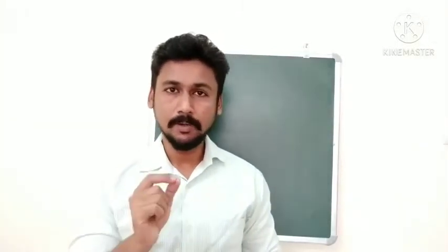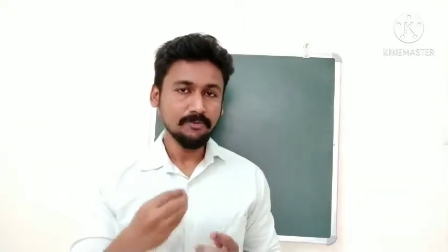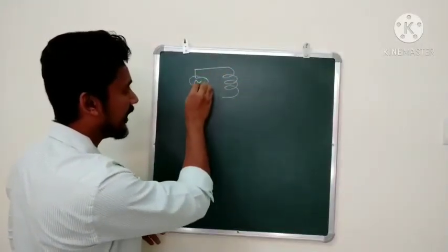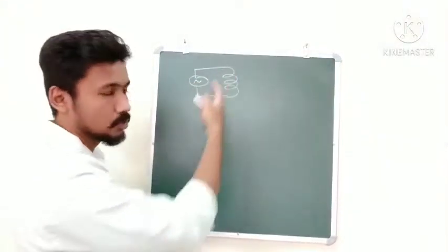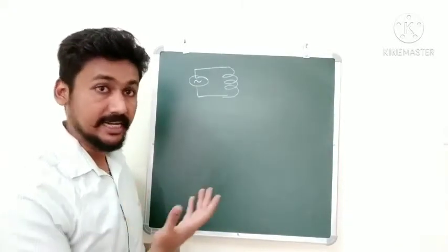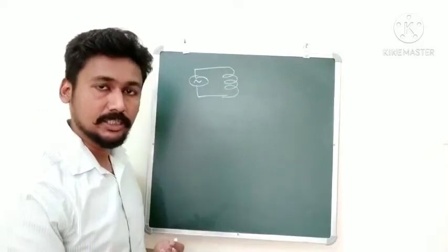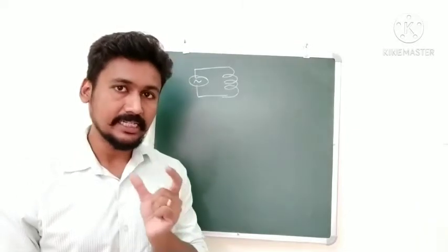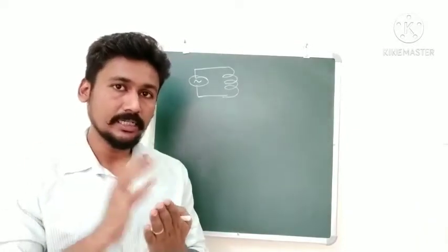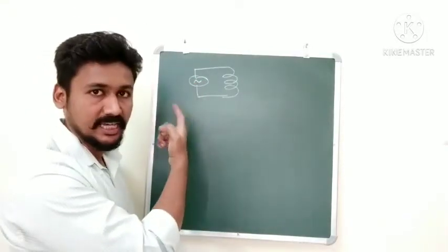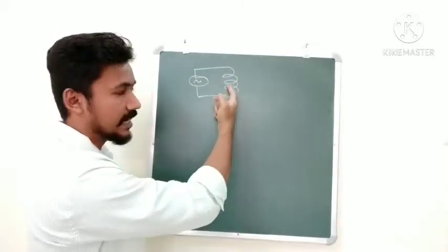Now once again let us talk about this phenomenon of inductance. When we saw the self-inductance, we were having a coil, and from that coil we were passing an AC current. As the AC current was going through the coil, it was having some self-inductance which was opposing the EMF that was created. The inductance was creating its own electric field, its own EMF. So basically what this inductance does is it tries to oppose the EMF that we are providing to it. This is the AC EMF that we have set up, and it is trying to pass some current I through the coil.